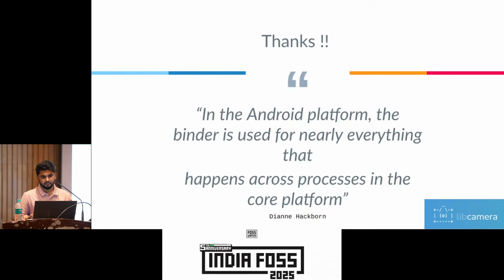Can this Libcamera also work on Qualcomm-based platforms? Because I know that Qualcomm has their separate camera stack. Yeah, so Libcamera will take the capability of the ISPs. If you know the underlying ISP hardware of the Qualcomm camera stack and you can add the support for that, then of course it will work. But for that you have to add the support. It will be difficult, as I believe everything runs in library format in the Qualcomm stack for ISPs.